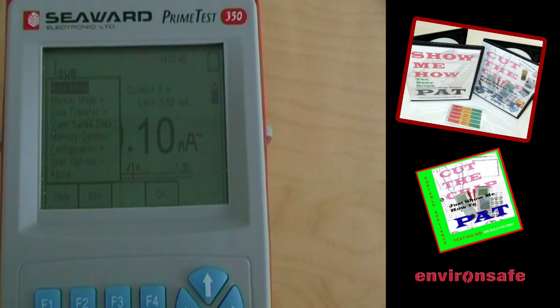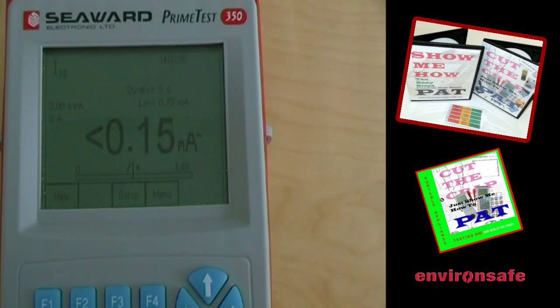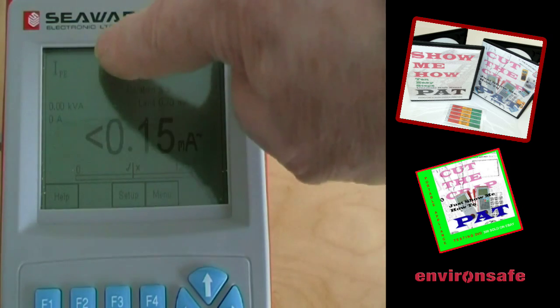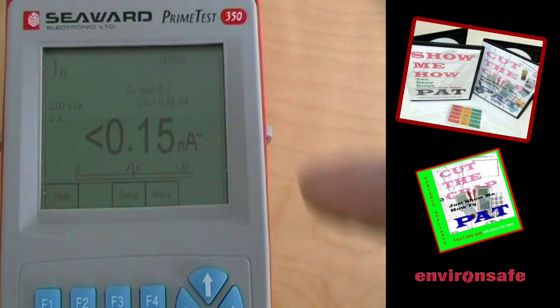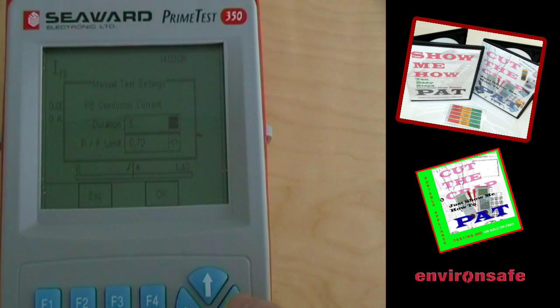Menu, F4 to select manual mode, PE conductor current, F4 to select. Now this is set at 0.00 kVA, so if we set this up, the duration options are as before, from 2 to 30 seconds.